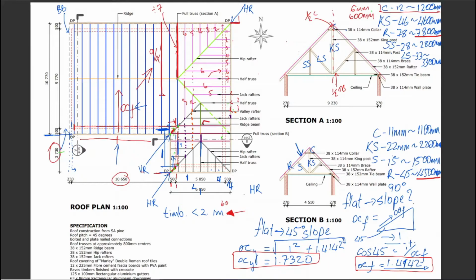Then maybe you want to go ahead and say, well, let's find out the divisions. 7, not 6. 7. And you go ahead and you find out your divisions. And then you do the same thing for the smaller side. You find all your divisions. And to me, it's just better to do all of that up front than to have to jump between describing, then doing analytical work on your drawing, and then going back to describing.